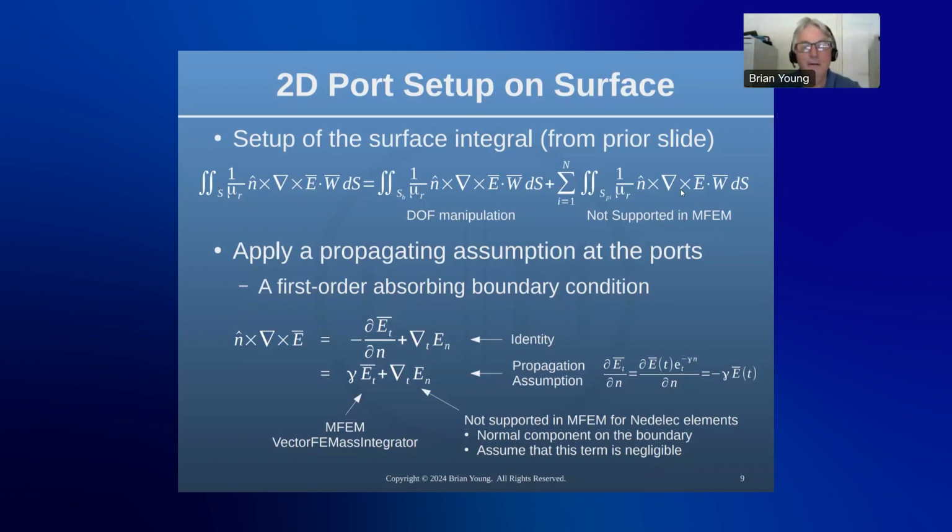How big are these systems? Because if they are not that big, a direct solver will handle this. I go up to a couple of million DOFs. Oh, okay. Is that considered small or large? It depends. On a laptop, it will be large. No, I'm running on a big machine. A dual slot, dual CPU Xeon machine. Yeah, this would be considered large, I would say. On a large machine, the direct solver will handle this.